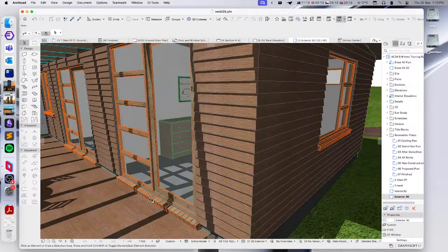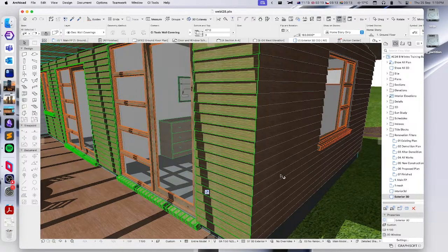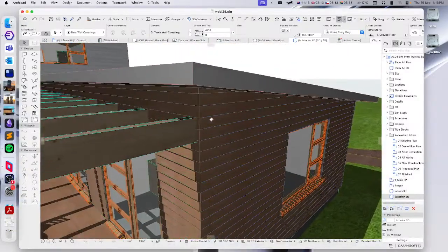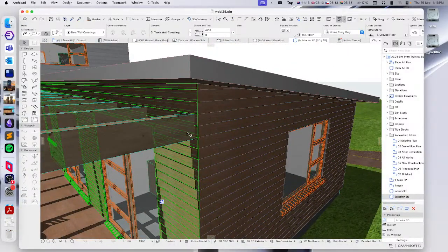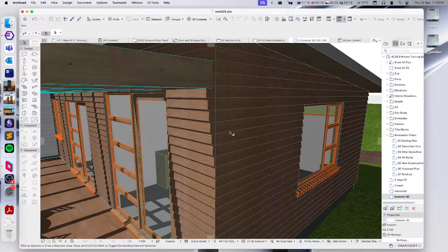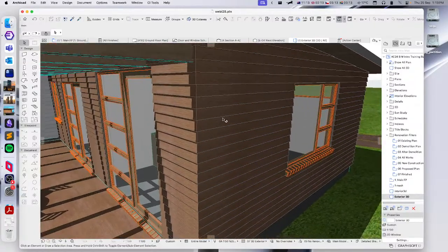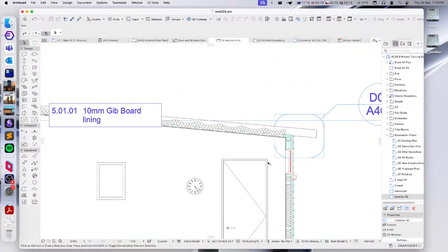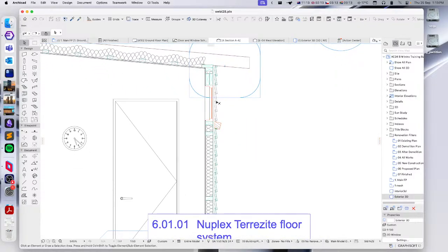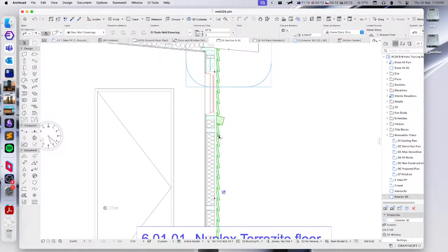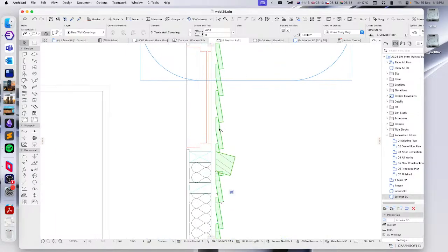We've also got some sills being applied as well. This is part of the covering, so it's placing sills underneath my openings, my windows and doors. You can also see that in the corner, it is mitering this wall covering to this one, the same as the walls are mitered underneath it. So it does pretty much what you would expect based on how I've described it so far. And if we jump to our section view, we'll also see it showing up there as well. Looking at our walls, this is our wall cladding here. So it's placed this 3D weatherboard here, which we're cutting through, so we can see the representation of that.